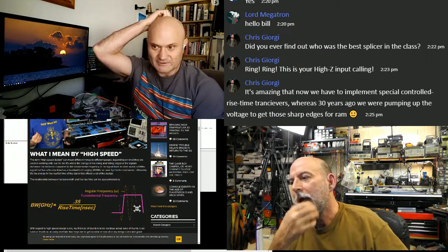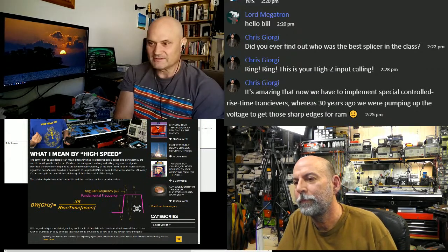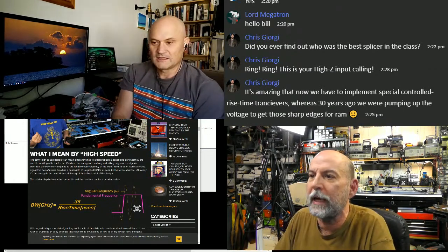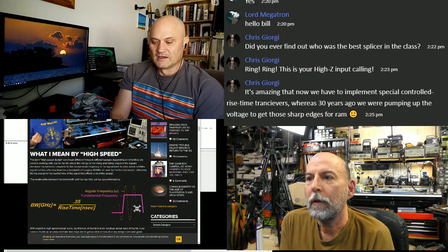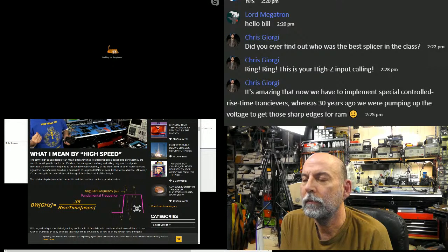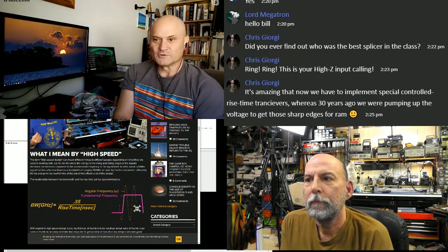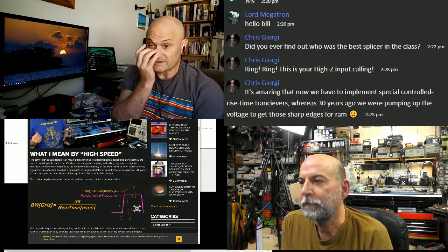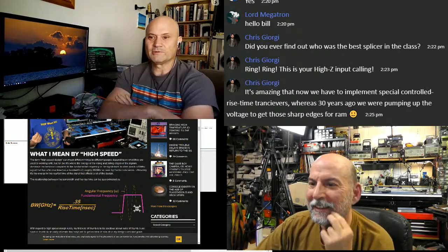So, and Chris, you're saying it's amazing how we have to implement special controlled rise time transceivers. Yeah, it's true. I mean, we're really spoiled in our FPGAs and stuff. We just slow them down. It's when we go back to the older stuff that we have to start watching our edges again sometimes. Well, or even discrete. And occasionally we still want to use one of those tiny little single or dual inverter gates. They become real popular. Yeah, the 1Gs and stuff. Yeah, we still need a little glue logic here and there, or some jelly beans. Yeah, popcorn components, right? Yeah, yeah.